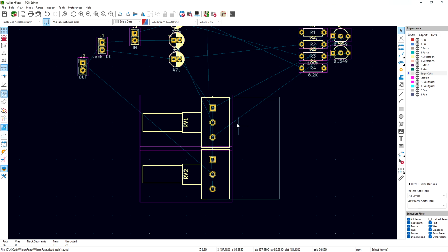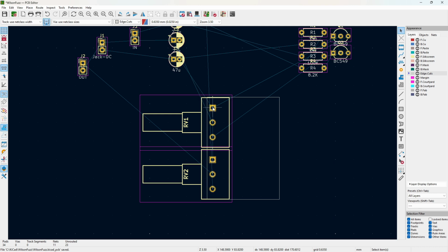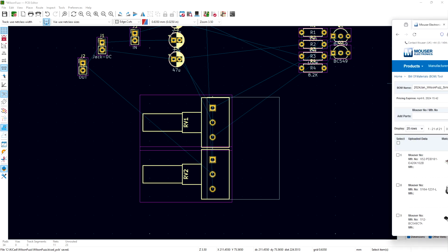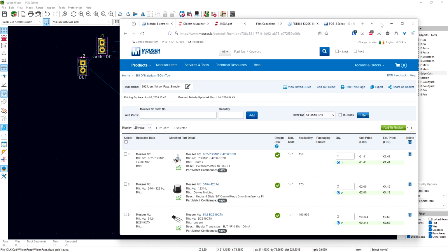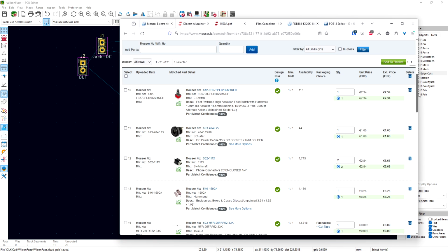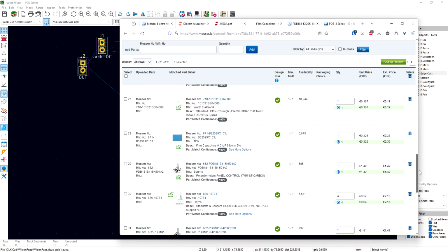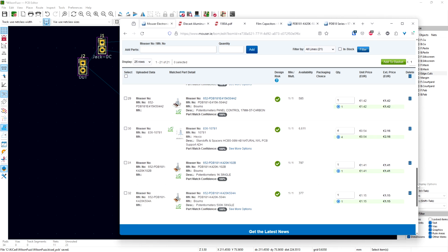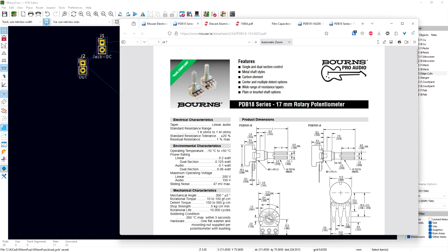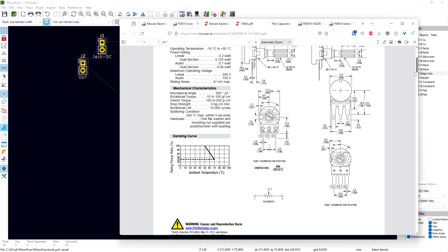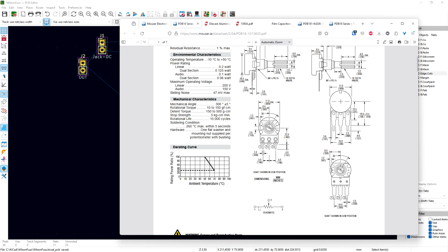One thing I noticed is that, see, this footprint is 1, 2, 3 here. Let me see, I was caught by this before. What I noticed was that the numbering does not look right on the pinout. So we see 1, 2, 3, and 1, 2, 3.